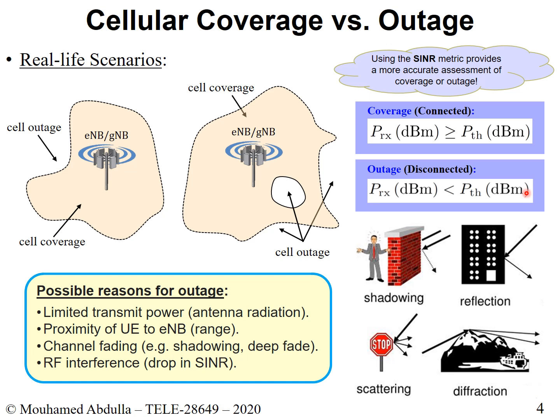Now, maybe I should mention it again in case you guys forget. You do recall that we saw this in the link budget, that the power that you transmit is equal to the power received plus path loss, right? That's what it is. And therefore, if you want to find the power received, you simply isolate for the power received.